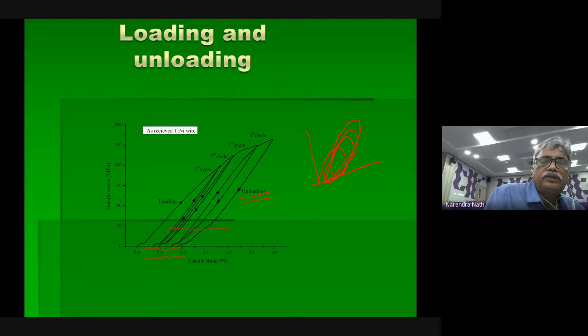But if you use a high-end Instron or any high-end tensile machine with dynamic characteristics, it comes like this. Going, so this is the plateau. It is coming back here, so that means exactly the origin. So no residual stress. If it comes with time like this, then this is the residual stress accumulated. So you need high-end, sophisticated measuring devices.